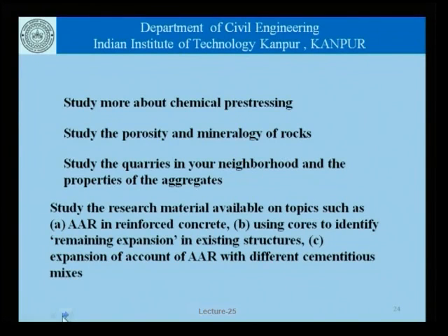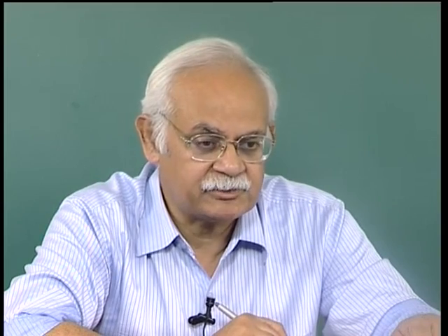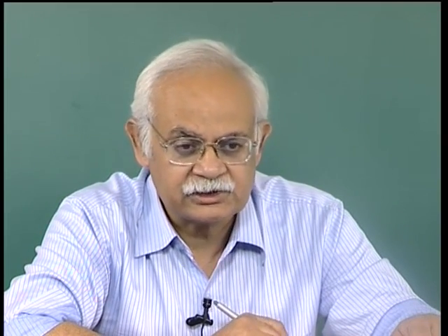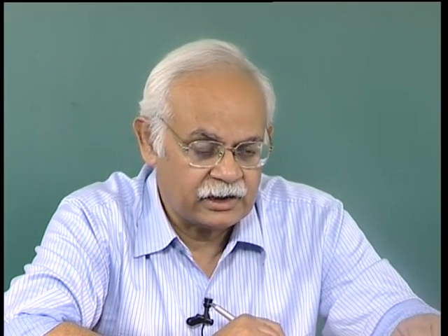We could study the research material which is available on topics such as the alkali aggregate reaction in reinforced concrete, use of cores to identify the remaining expansion in existing structures, and study the expansion on account of AAR with different cementitious mixes. And that is the kind of discussion which we were doing, or which is relevant from the point of view of controlling the expansion on account of alkali aggregate reaction by manipulating the cement content or the alkali content in the cement, controlling the cement content, using chemical admixtures or mineral admixtures to control the overall alkali content in the concrete.